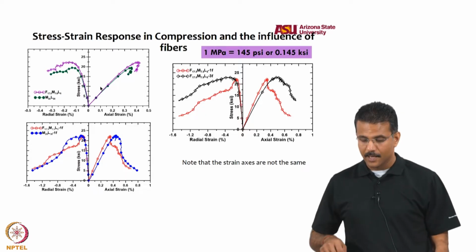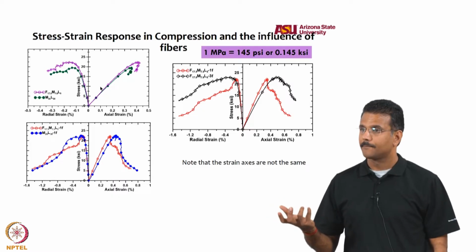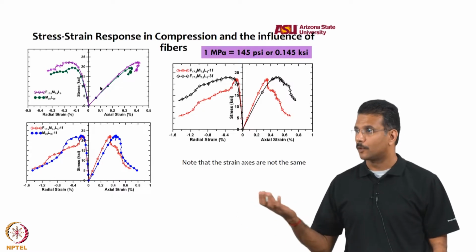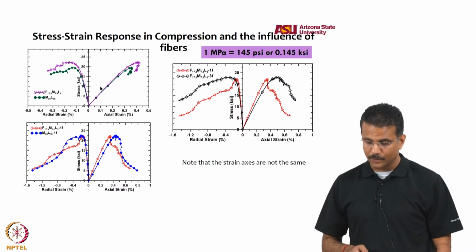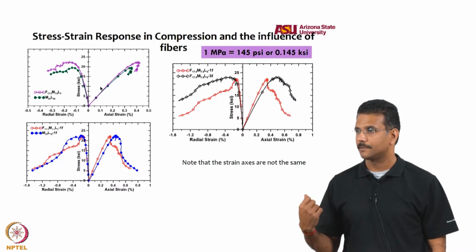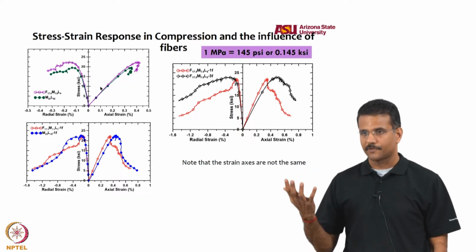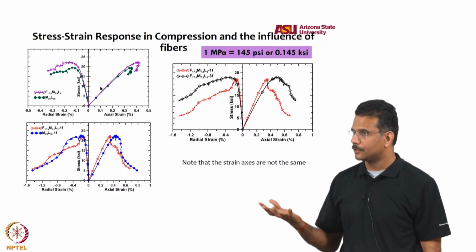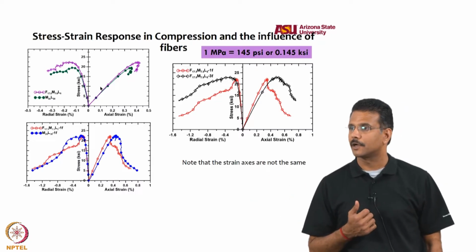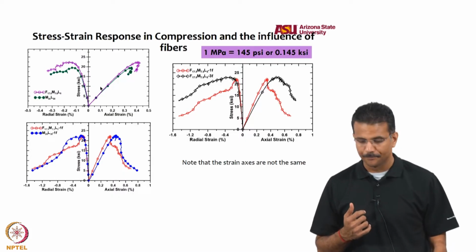The axial strain is increased obviously because your fibers are effective post first crack, and you will also notice that the maximum axial strain at the peak has not changed, it is still around 0.35, which means from a design point of view that is what you should use, because in reinforced concrete design you look at what is the strain at peak load.